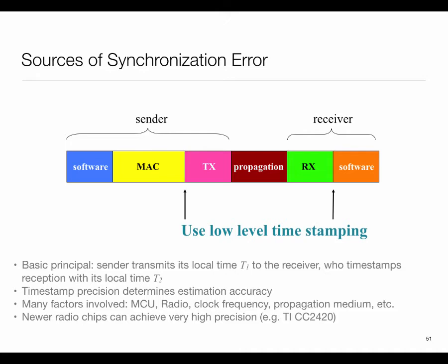So I'm trying to timestamp this signal which is saying packet is being transmitted. I tied it to an interrupt, let the interrupt handler fire. Within the interrupt handler, I read the timestamp. What sources of error do you see in that? The delay from the interrupt fire and the process. Okay, and what would affect that delay?